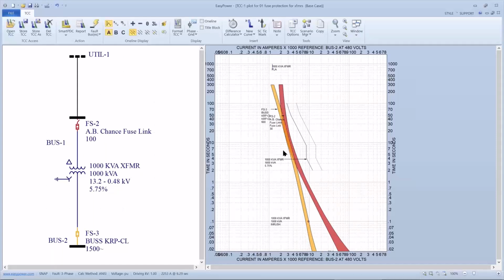And it's a case where I may want to accept miscoordination because I have the primary fuse lower because of this derated curve. So that would be something I would consider for coordinating both the secondary and the primary side for transformer protection.